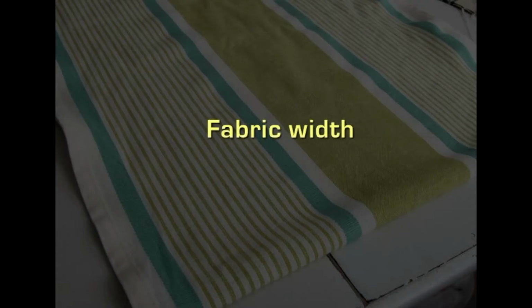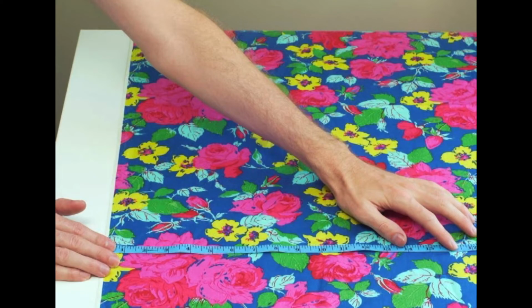Then coming to the fabric width, how are we going to measure this one? In this also, similar to length, each measurement has to be taken to the nearest millimeter, with the steel rule resting on the fabric in a direction at right angles to the selvage. Fabric folded down the middle, if received in that state, may be relaxed and conditioned in that state, but all measurements shall be taken from edge to edge with the fabric open and laid flat.